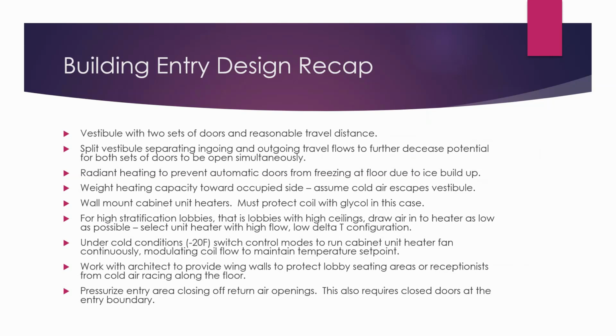in initial construction, we had everything that we thought we could do. We had radiant heating below these security guards. We had cabinet unit heaters. We had a good entry, and yet they were still freezing. And so we did one more modification because we had doors all around this 2-story entry. We were able to close all those doors, and we were able to close off the return air openings out of this vestibule and pressurize the vestibule. And so that was the last thing we did, and it helped quite a bit.